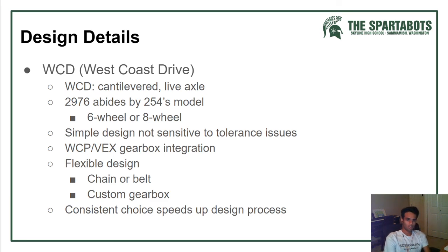It's a simple design, and it's not sensitive to tolerance issues. Make sure your designs are simple and not sensitive to tolerance issues, so you're not always going to be exactly precise with the CNC router or when you're match drilling things. So make sure you can accommodate for those issues. Using COTS gearboxes can save you a lot of time.